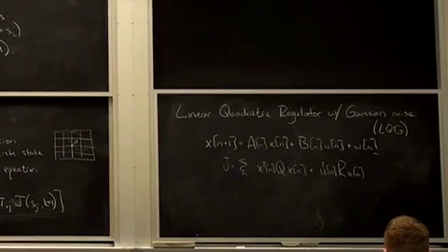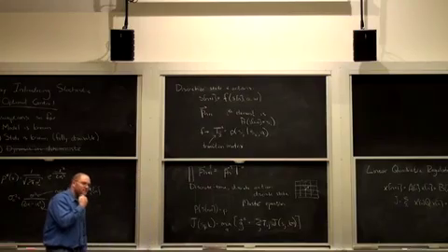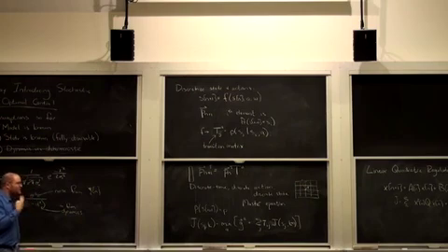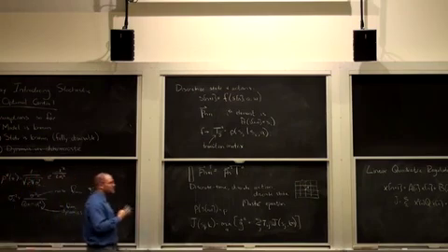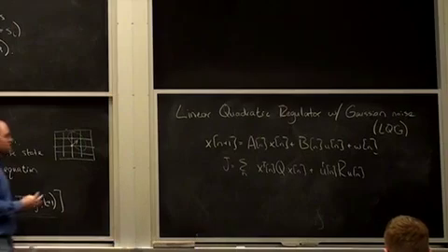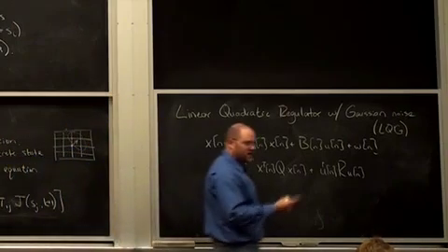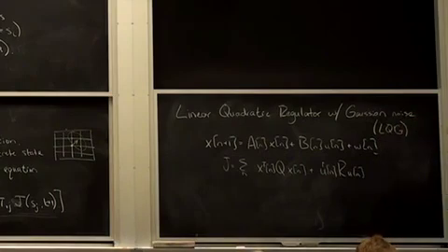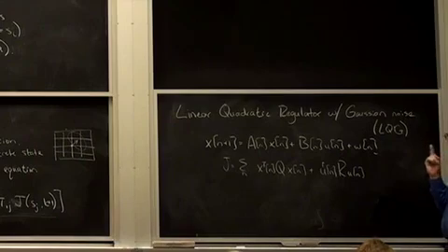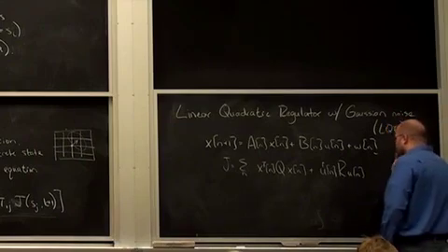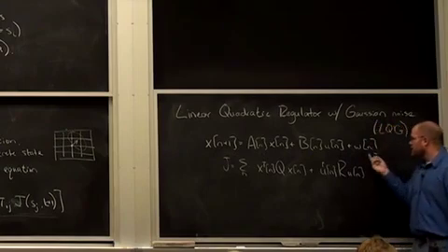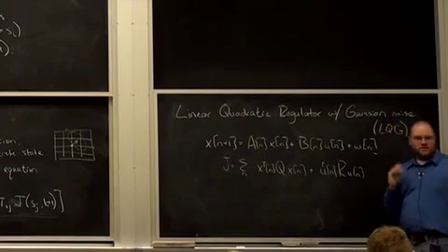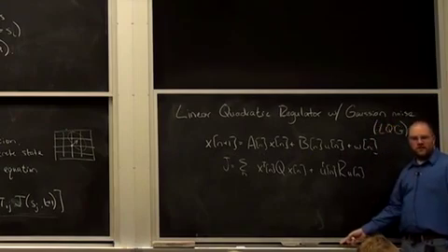What do you think is going to happen with that problem? If someone hasn't used it extensively in your work, what's going to change about our LQR solution? Think about stabilizing the pendulum. Let's say we're doing optimal control on the simple pendulum, linearized around the top, and now there's disturbances bouncing me around. How would you act differently given some model of the disturbances in the linear case?